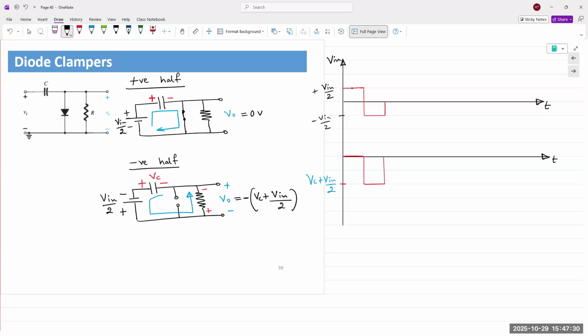So these kind of clamper circuits are also part of the diode wave shaping family. Okay. So there are multiple variations on this. Flip and clamp is we are clamping the level of the voltage waveform. Either we are clamping it above or we're clamping it below. Yeah. One application of clamper circuits, we will see when we do amplifiers, BJT amplifiers.